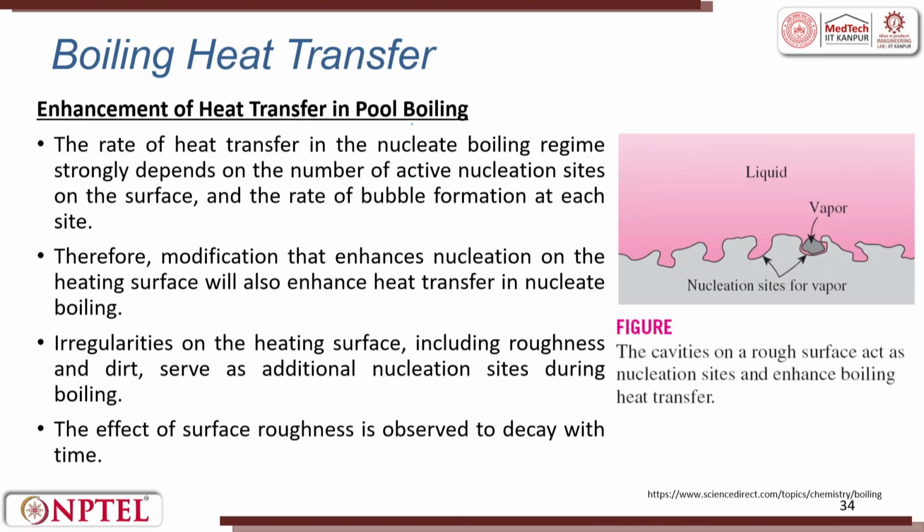Enhancement of heat transfer in pool boiling is very important. Here we have liquid, this is vapor, and these are nucleation sites for vapor. The rate of heat transfer in the nucleate boiling regime strongly depends on the number of active nucleation sites on the surface and the rate of bubble formation at each site.